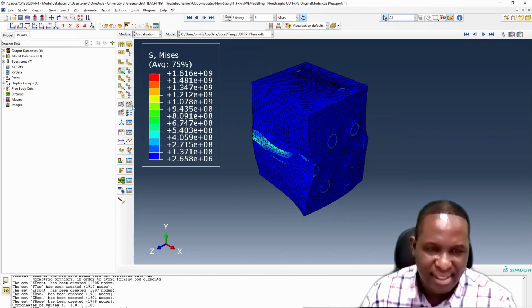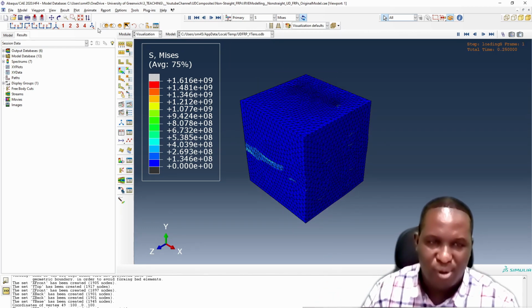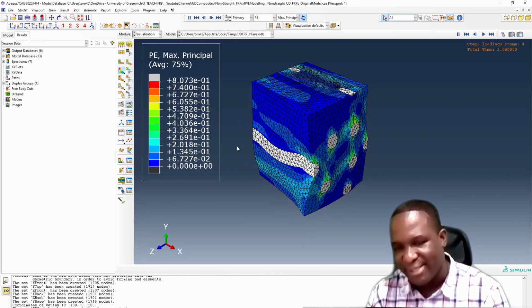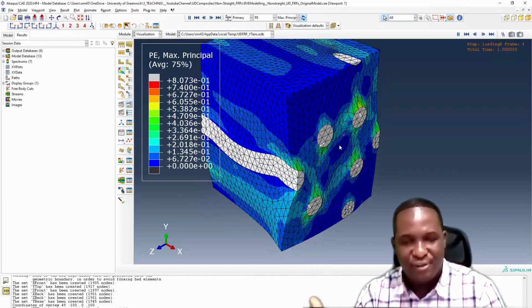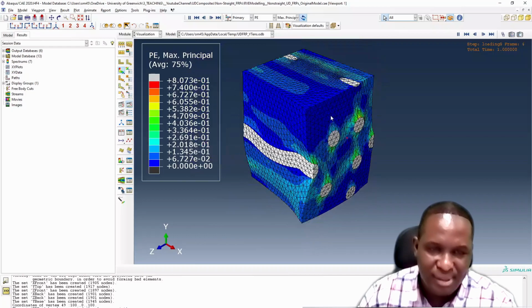The Y tensile case obviously requires you to move up as you push the system up as well. So what about the plastic deformation? You can see there's a little bit of plasticity because the matrix is really sheared, experiencing a lot of finite deformation, and the fibers are kind of moving around in space. So that's what we get.